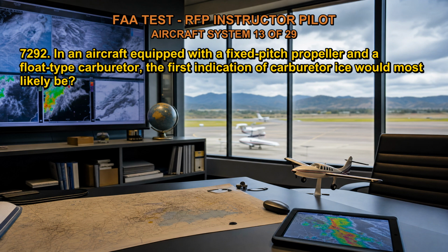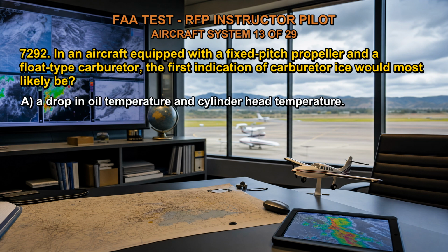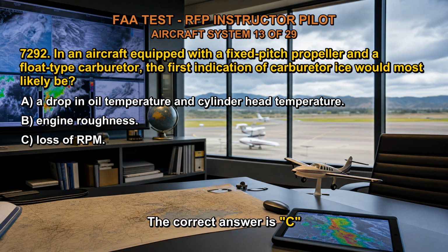Q7292. In an aircraft equipped with a fixed-pitch propeller and a float-type carburetor, the first indication of carburetor ice would most likely be: A. A drop in oil temperature and cylinder head temperature. B. Engine roughness. C. Loss of RPM. The correct answer is C.